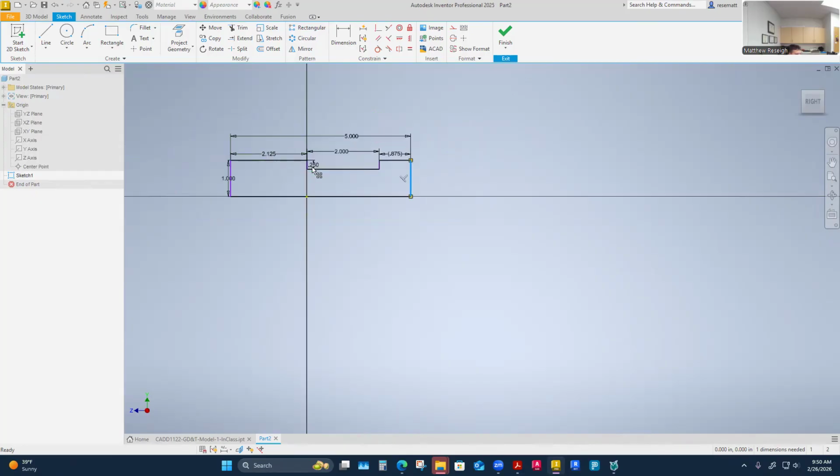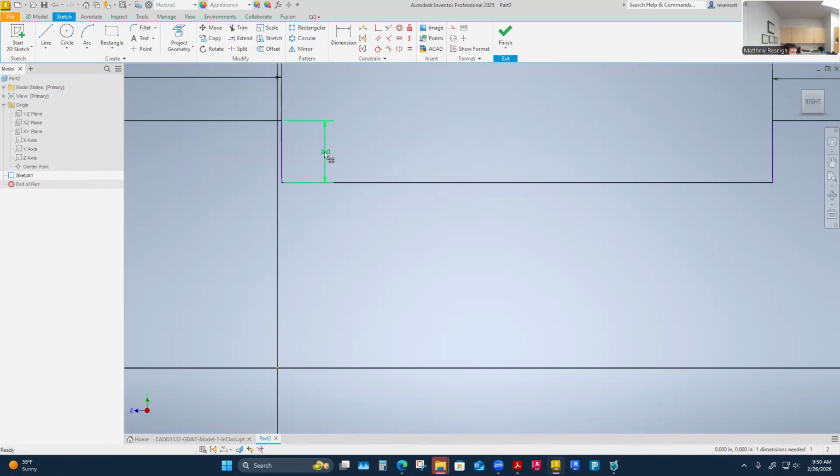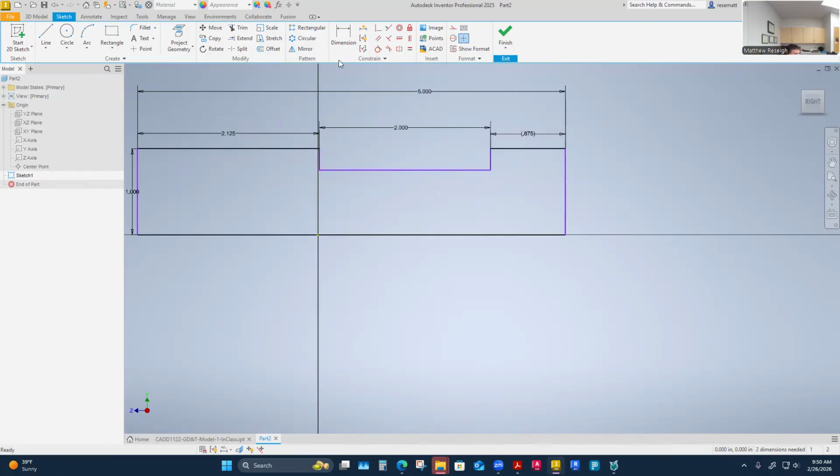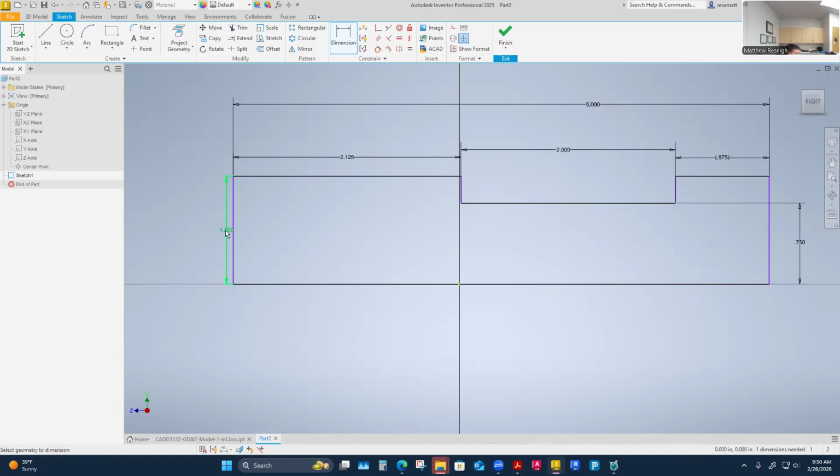And I could even change this one and say, I knew I drew this originally there, but maybe that's not the dimension I'm going to ever use to manipulate this. Really, I like this dimension better from here to here. That's 0.75. Only because that's really from a datum control there. So I'm kind of patterning my sketch after what I would expect to get if I was looking at the drawing and I decide there's some things wrong, I've got to make some revisions. When I jump into the sketch, it's going to resemble pretty close to what my drawing looks like. So it's not going to be this other whole curveball that I've got to diagnose and figure out what to drive where.